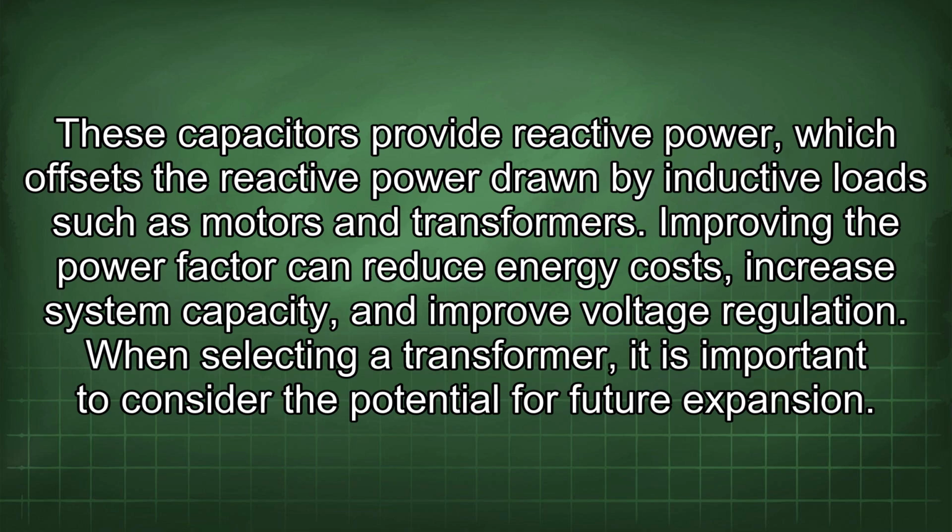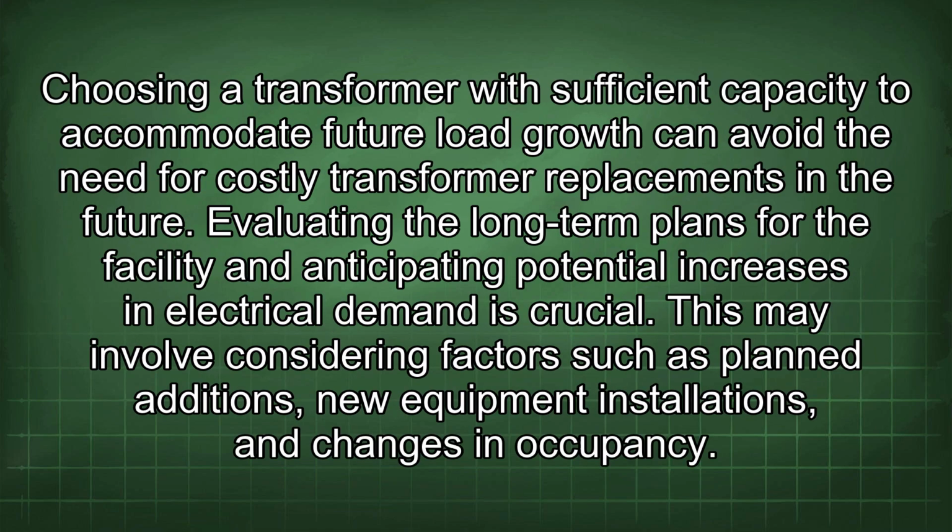When selecting a transformer, it is important to consider the potential for future expansion. Choosing a transformer with sufficient capacity to accommodate future load growth can avoid the need for costly transformer replacements in the future. Evaluating the long-term plans for the facility and anticipating potential increases in electrical demand is crucial. This may involve considering factors such as planned additions, new equipment installations, and changes in occupancy.